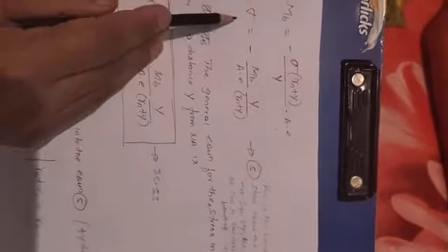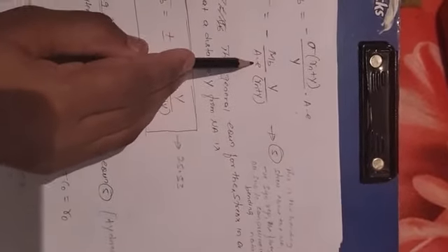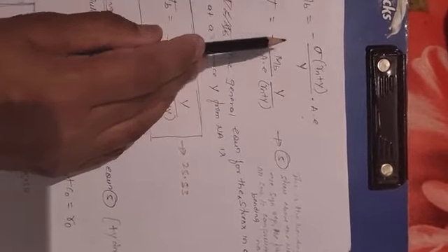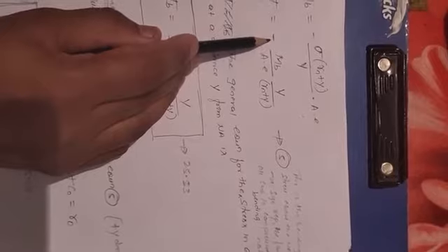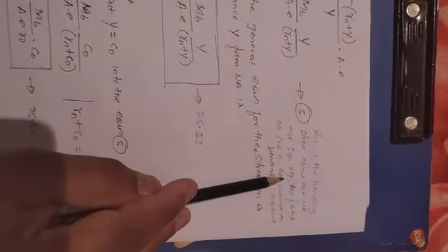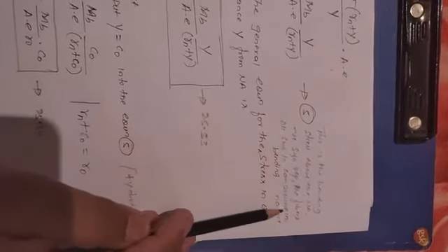Then from this, our aim is to determine bending stresses. Sigma is equal to minus Mb by A into y divided by Rn plus y. Why does the negative sign come? We consider that above the neutral axis the fiber undergoes compression. That's why the negative sign is there. Now, equation 5 is the bending stress above the neutral axis. The negative sign represents that fibers are subjected to compression.